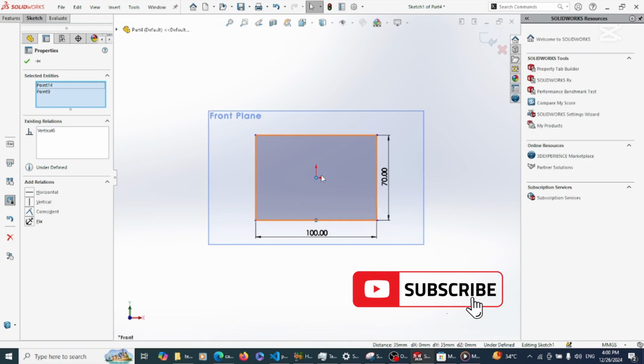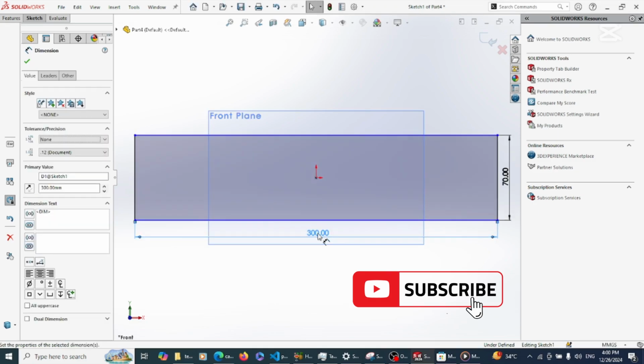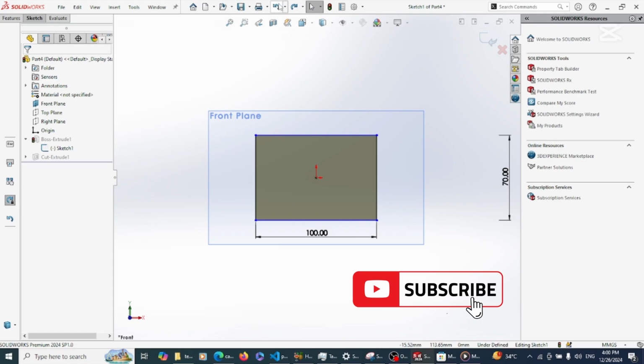They are locked vertically. It means it can't dance around at any angle. So it means that this guy will always be half of it, probably at the center. So if I change the dimension now to 300, it's still going to be at the center. It's not going to shift. Good. Control Z is to undo, or you use this undo.